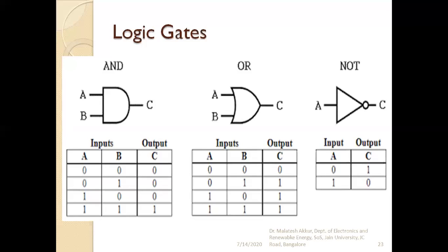The digital circuits basically mean the logic gates. The logic gates are the building blocks of any digital system, or the computer, we can say. We know the classification of the logic gates as the basic gates, the universal gates, and the hybrid gates. The basic gates are what? NOT gate, OR gate, and AND gate. And the universal gates are what? NAND gate and NOR gate. The hybrid or derived gates are what? The XOR gate and XNOR gate.